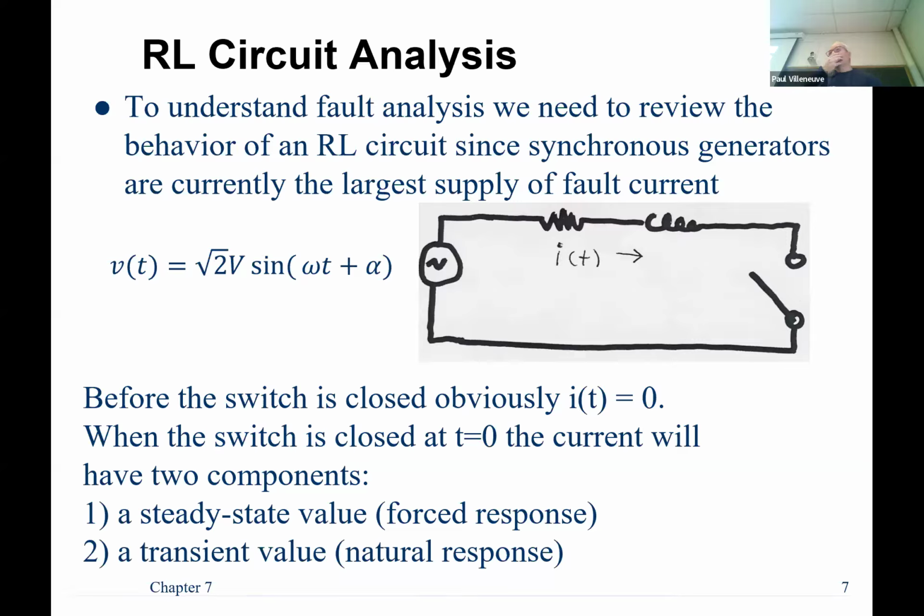Yes, sir. What do you mean by the breaker can't interrupt the fault? Because if I have a breaker that's rated for 100,000 amps, that breaker might initially, for a very short period of time, see 160,000 amps going through it. If I tried to open that breaker when there's 160,000 amps, it's too much force. While it's pulling open, the force is trying to keep it closed. And so the contacts actually bend, and then you can't open it.